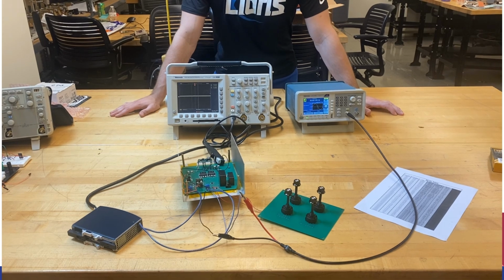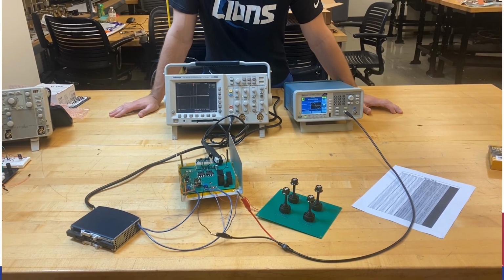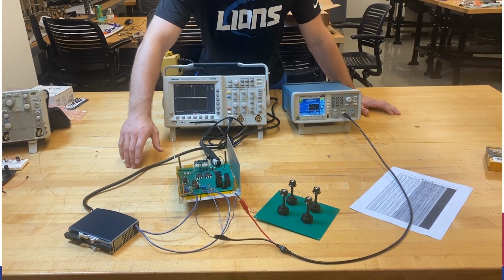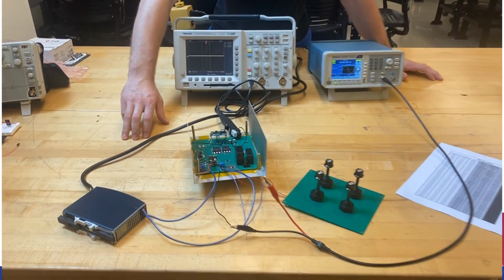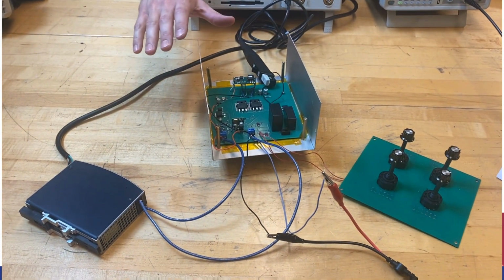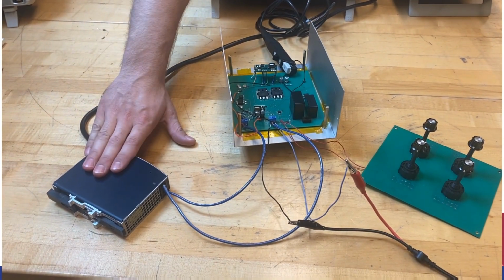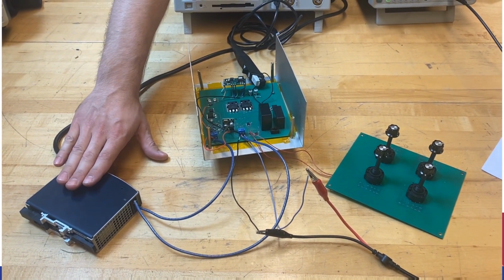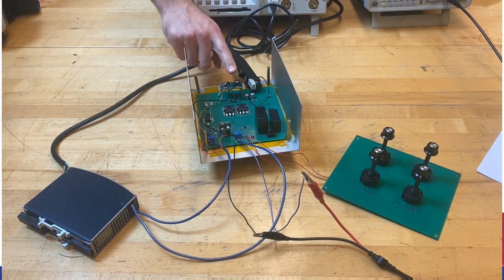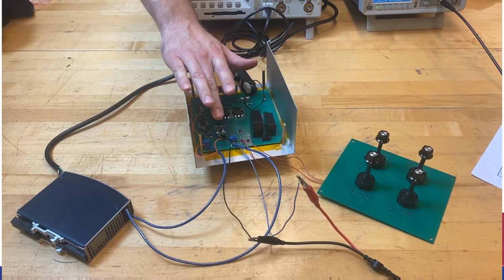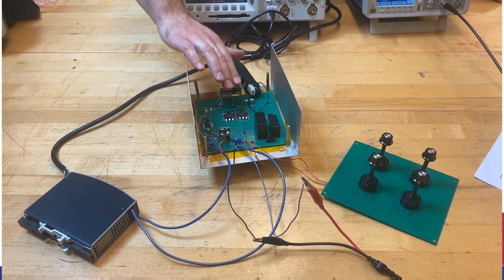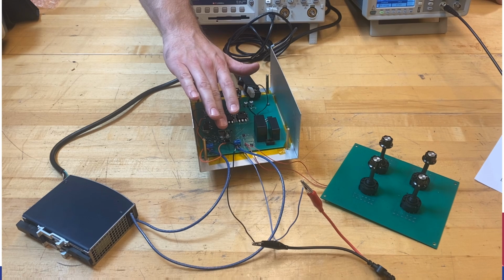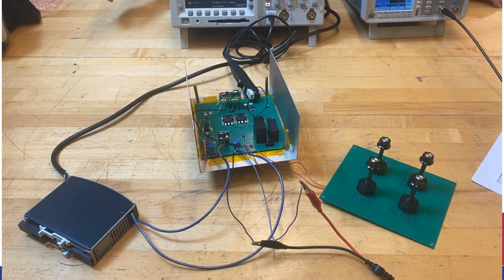Hello everyone, this is our Rogowski Coil Integrator prototype, so if you want to come in and take a look, to start off, just for power, we have a power supply here that's supplying 24 volts, and then that's going into two voltage converters, which is a negative voltage converter and a positive voltage converter here. This is for negative 9 volts, and this is for positive 9 volts.